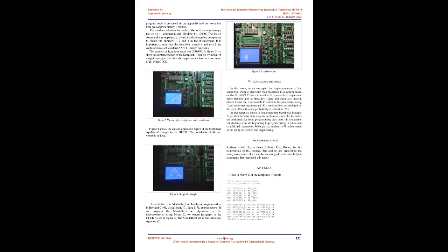3. Microcontroller PIC. A PIC is a programmable integrated circuit that contains the architecture to perform different tasks, which is why it is called a microcontroller. In order to classify the PICs, they are put into 3 families according to their capacity. These families are 8 bits, 16 bits, and 32 bits. These in turn have subdivisions by the ranges of microcontrollers that we can use.